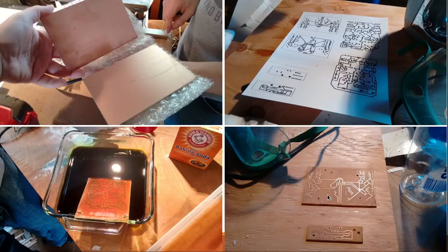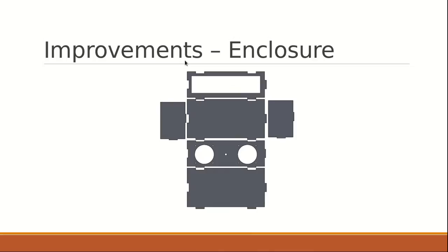And so the enclosure was made in SolidWorks. Here's the front of the enclosure. We have the two speakers and their drill holes and the knob cutout. And then the back, since I didn't know which board I was going to use in the final version, I just had the back open, so that way either board can be fit in, and I didn't have to make a final decision on a panel cutout. And it also made it easier to access and screw in the speakers, because I assembled the box before putting the speaker in, and I was able to do that because of this open back.